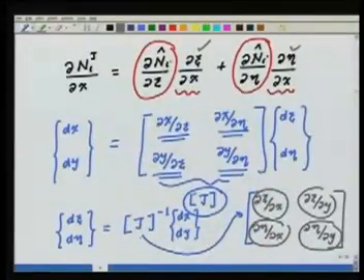The determinant of the Jacobian matrix can become 0, and the inversion may not be possible. That is, many points are going to one point or vice versa. That is, the mapping is not one to one anymore. So that's why we need to have the shapes of the elements or the quadrilaterals in such a way that the angles are always less than 180 degrees.